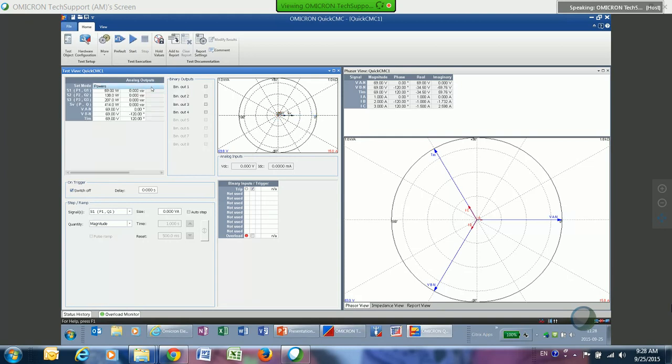And if I want, I could look at symmetrical components, and this is going to show my positive, negative, and zero sequence values for my currents and my voltages. If I want, I could use powers, and it's going to show power values here, watts and vars, both single phase and three phase. I could do fault values if I want. If I choose, I could do an impedance with current constant, impedance with voltage constant, or an impedance with our source impedance constant. And then you can do percent impedance here if you want.